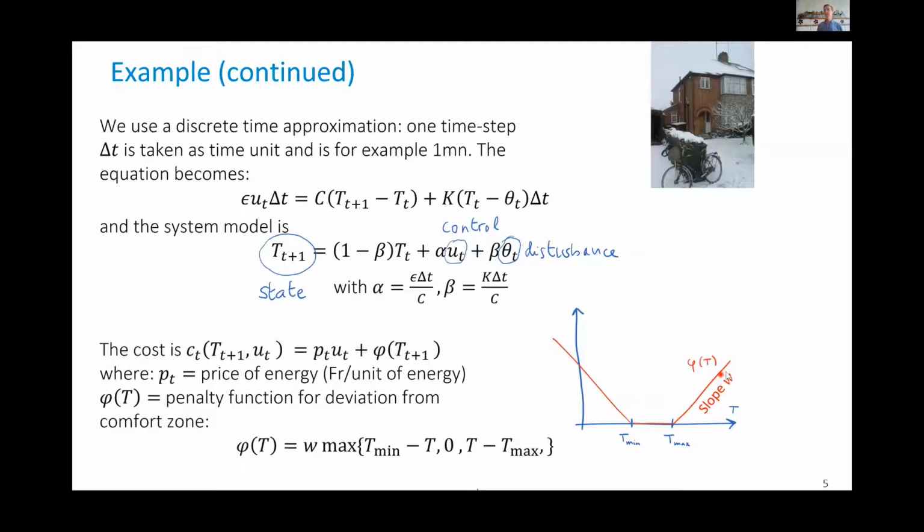So to avoid this, if some of the constraints are not really hard constraints, if, for example, the temperature is not between 19 and 21, but goes to 21.1, then the system will not collapse. So that is what we call a soft constraint. So such a constraint where we can exceptionally accept a violation without any major dysfunctioning of the system, then it's better to put them as soft constraints.